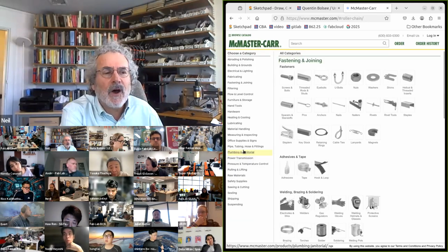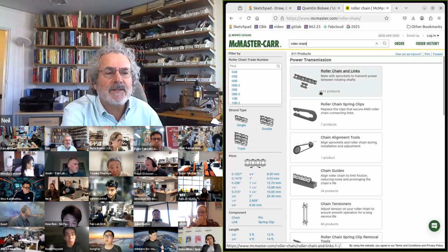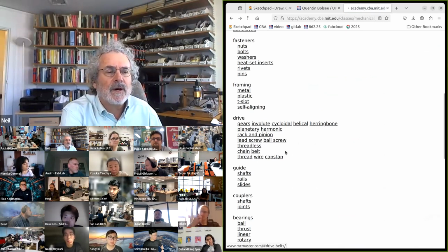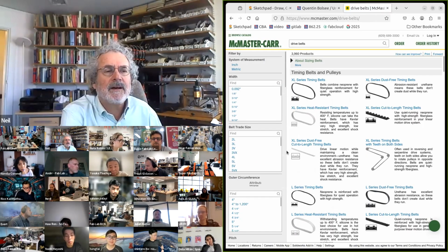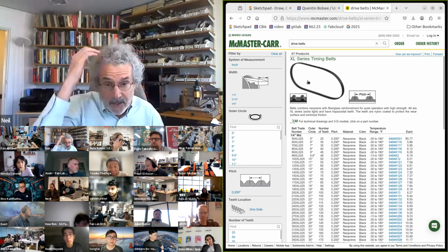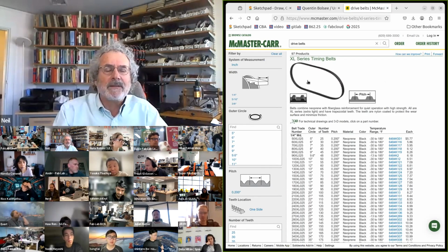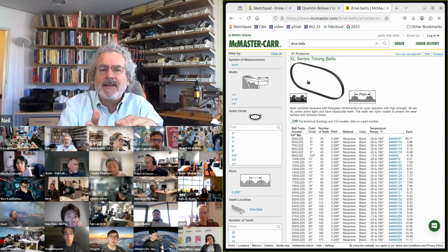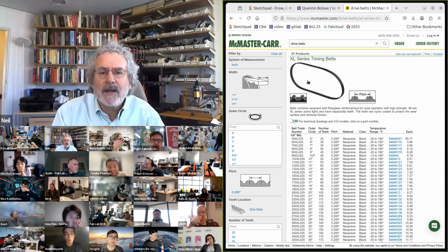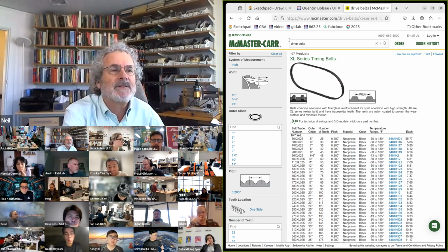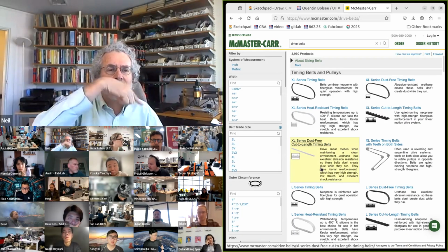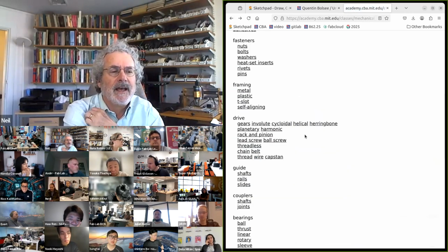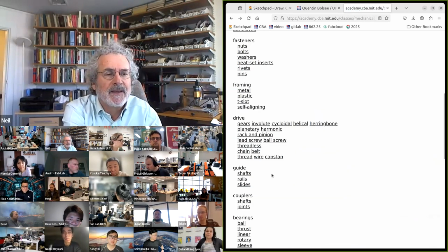Then for large forces, you can use chains, but with a chain the force is very uneven. So a lot of use gets made in machine building of belts. These belts look like a floppy rubber belt, but they're internally reinforced, so you can't stretch it. The space between the teeth is controlled, but you can bend it. And so you route these timing belts around pulleys and use that to distribute forces in the machine.